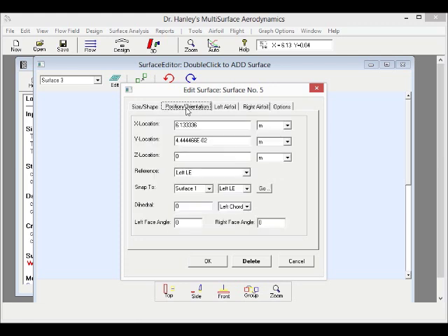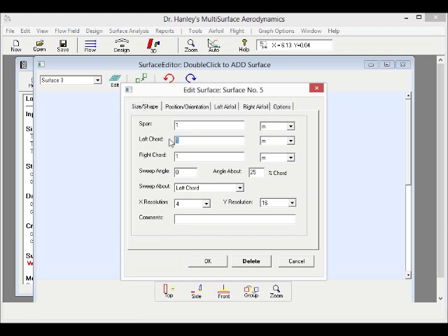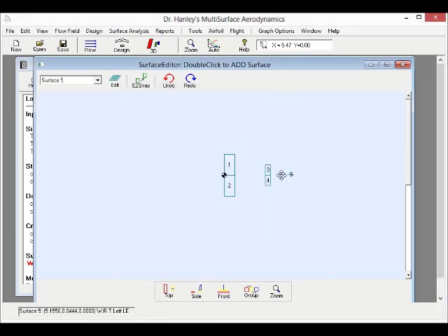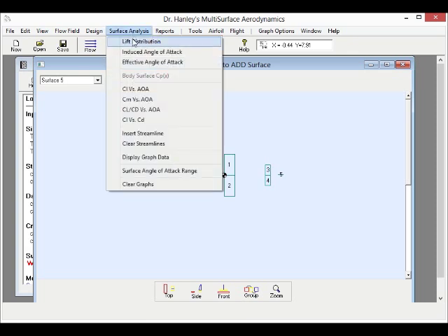here in this example we're going to add a vertical stabilizer to our model airplane that we're building, and we're going to then look at the stability again to see whether or not we have sized the surfaces correctly, and to see whether we have the desirable performance. So we added the vertical stabilizer. We take a three-dimensional look at it and see